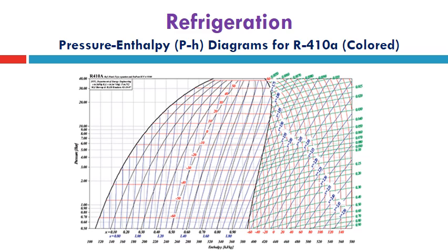We can find the same ISO lines, and we confirm here that the temperature lines inside the wet region are horizontal and identical and typical to the constant pressure inside the wet region for this kind of refrigerant, which is recommended rather than 407C due to its stability for condensation temperature and evaporating temperature rather than 407C as discussed in the previous slide.